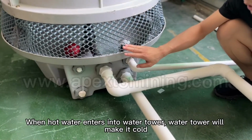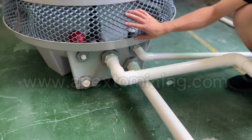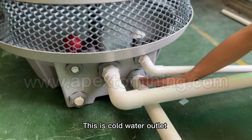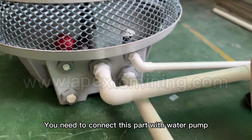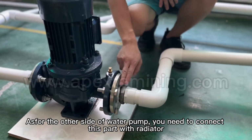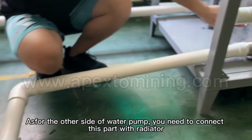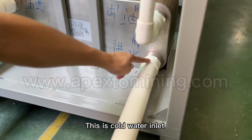When hot water enters into water tower, it will become cold. And please look at this part. This is cold water outlet. You need to connect this part with water pump. As for the other side of water pump, you need to connect this part with radiator. This is cold water inlet.